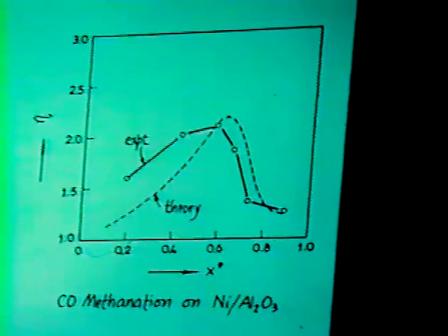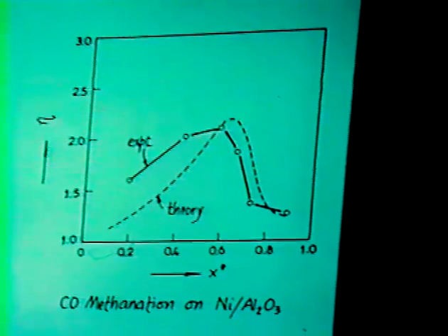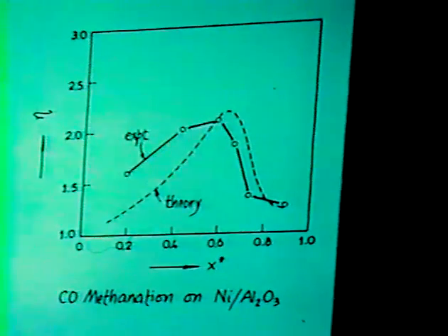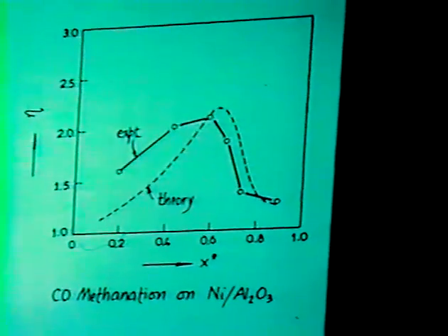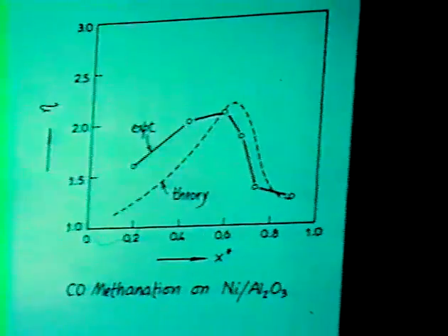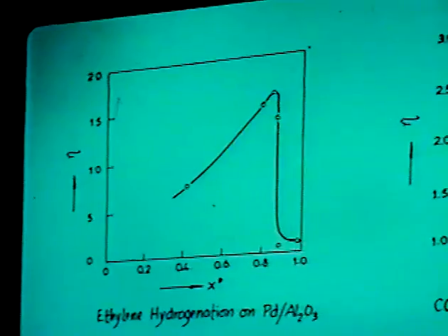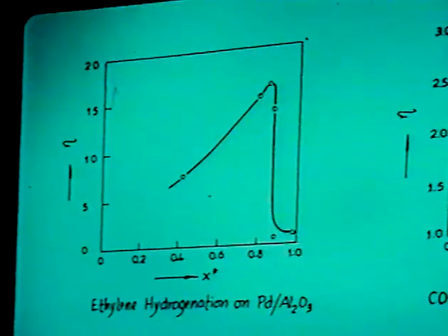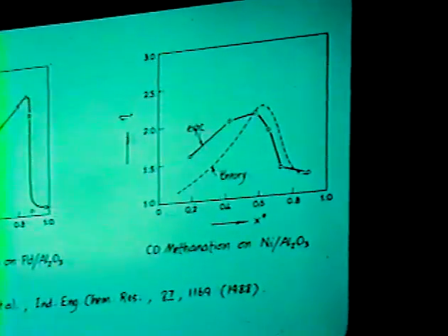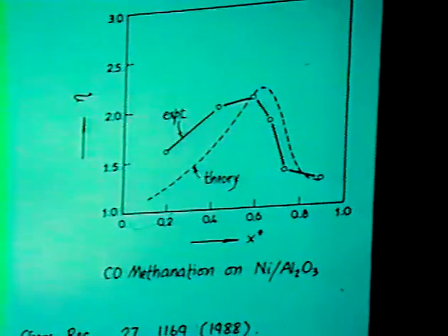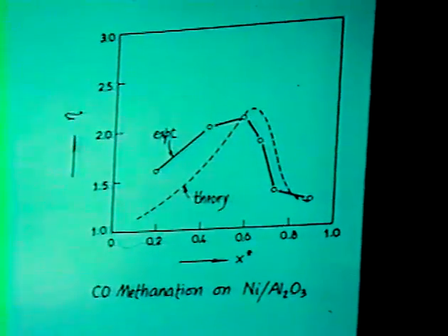In this case, by the way, the reaction is very highly exothermic. So although it is positive order in the kinetics of ethylene and hydrogen, it is highly exothermic. So we are taking advantage in this case of the reactivity at a higher temperature at the location of the catalyst, and therefore one gets a very high effectiveness factor, because where the catalyst is located, since it's inside, that's where the heat is generated. So the catalyst is hot at that stage, it has a higher activity than it would have if it was all on the outside.